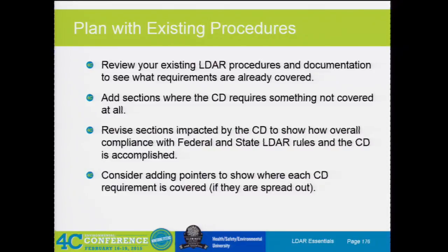So you're going to have your federal regulations. So you've got your MACT CC, so there's your 10,000 ppm level. Well, now you might be in an NSPS GGGa unit, so now you have to put that rule set onto that component, and now its leak definition is 500. Then if you're in South Coast, they have their own 1173, which has a 200 ppm leak definition. So now you have to apply a whole other rule to this one component. So just in that one valve, you could have 3 different rules. So what are you doing here? You're showing how you're going to comply. A lot of folks, when they put this together, look in their database, and they're able to see what rule sets they have and what is applicable. And by that, they can just put that into their plan of here's how we're complying.